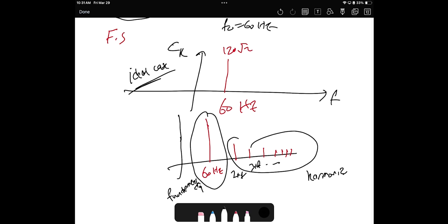Like what? You know electronics: diodes, transistors, rectifiers, which we used for AC to DC conversion, right? And we used it a lot, in cell phone chargers, in laptops. Whenever there is a rectifier, this will cause some harmonics. Whenever there are nonlinear elements, this will cause harmonics. So actually, your cell phone charger has an impact on the power. Any electronic device has an impact, a bad impact. So these electronics cause problems.